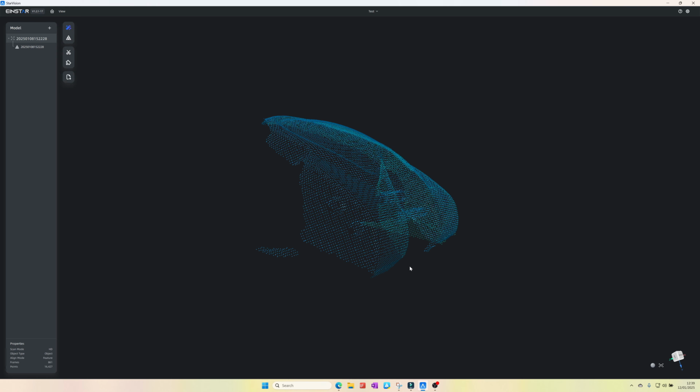Selecting a portion of the main domain with the lasso tool, I instruct the software to link all points within this domain. The software connects the points, leaving separated portions unaffected. If there were multiple such portions, you could select the main domain, expand the selection, invert it, and delete the unwanted islands. After cleaning up the points, finalize with Finish. The cloud is now clean and ready for mesh generation.